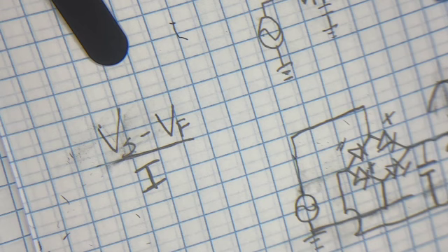The maximum values. Okay. Well, our maximum is 30. We don't want to do the maximum, but we'll do 20. So this says our resistance that we're looking for is about 345 ohms. I do not have a 345 ohm resistor, but I do have a 390 ohm resistor. So we will use the 390 ohm resistor.